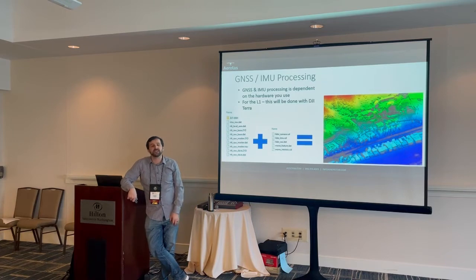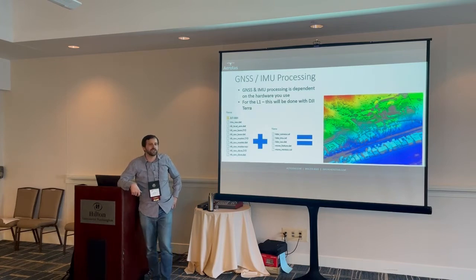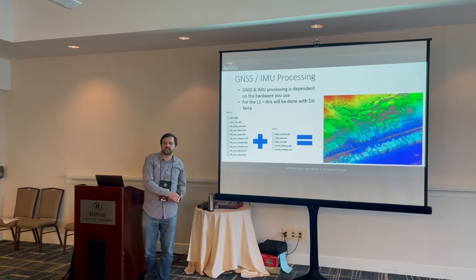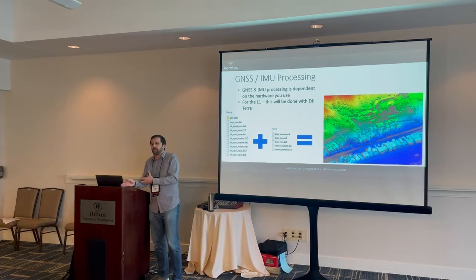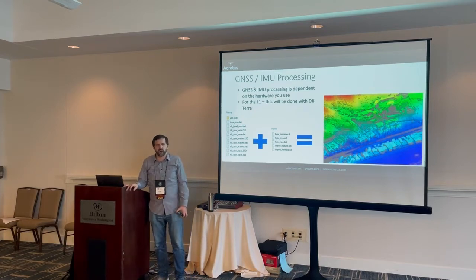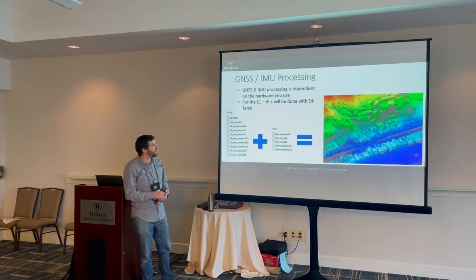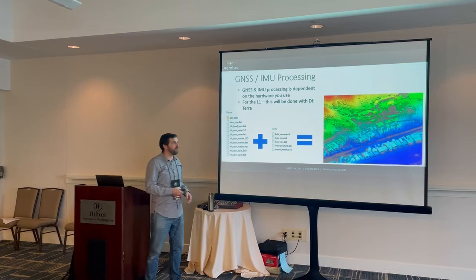A lot of these softwares just have glitches in them. That's what software does. Sometimes there might have been a glitch recording the GPS base station data, and you need to sub out your local base station for a network corrected base station RINEX data or something like that. It's fairly uncommon, but it is an important step, and it can be a source of error down the line,